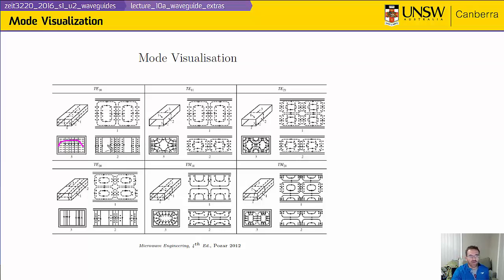What we're looking at here is down the path. So as I go down this line, that's going in this direction on the central axis of the waveguide. So we see the fields point up here, and then down here, and then up here, and that's the guide wavelength.